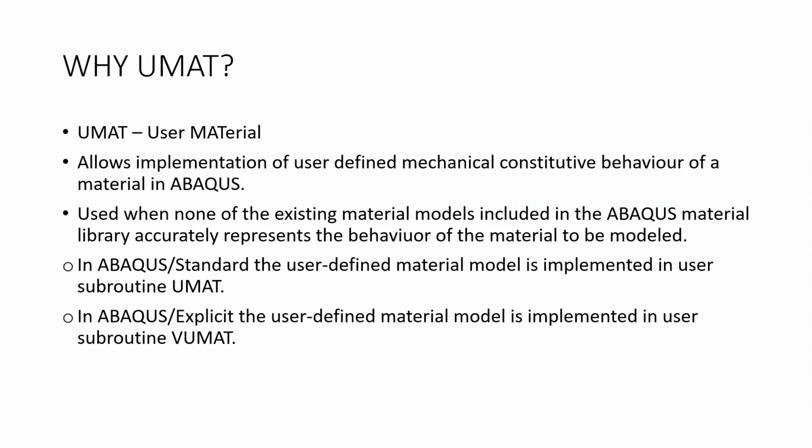The question may arise. UMAT is a short form for user material. What UMAT basically does is it allows us to implement any user defined mechanical constitutive behavior of a material in ABAQUS. If we have a material behavior which we need to implement, but none of the existing material models in the ABAQUS library can accurately describe it, then we go for writing a user subroutine to describe the mechanical constitutive behavior of the material.